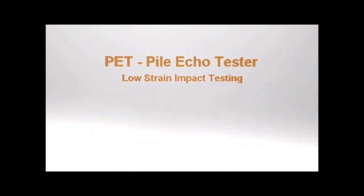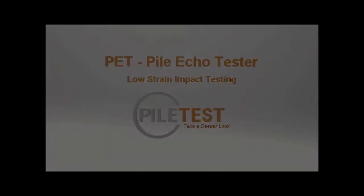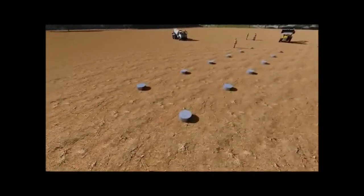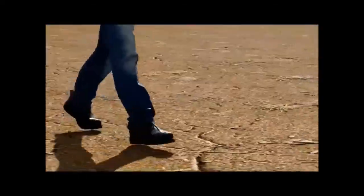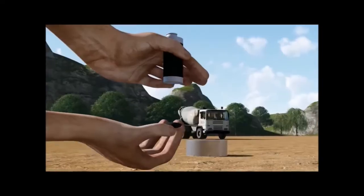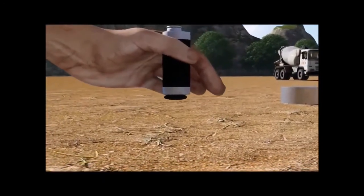PET, Pile Echo Tester, Low Strain Impact Testing. The mission: test the integrity of 12 concrete piles on this construction site. The tester goes to the first pile and prepares the top for testing. A small amount of special putty is attached to the bottom of the PET.